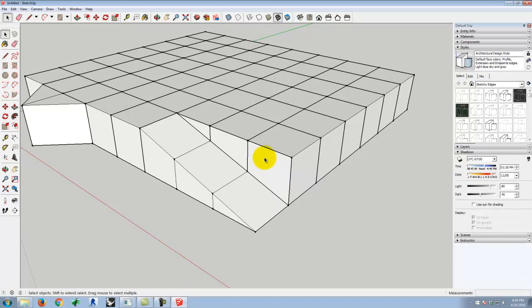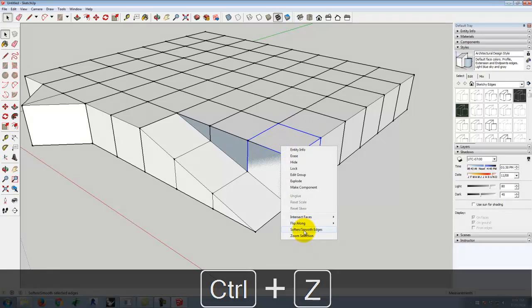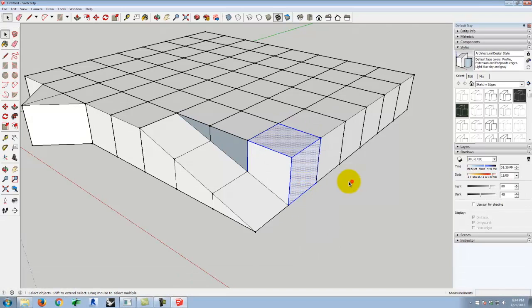The other option is if I ungroup this object, for example. So let me explode it. It turns white because when you have 2 coplanar objects in SketchUp, as long as they are not grouped, they'll join together and become one object. It's the way SketchUp works.